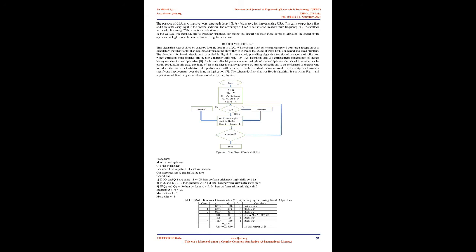Wallace tree multiplier. A Wallace tree multiplier is a hardware implementation of a digital circuit that performs multiplication of two binary numbers. Wallace tree multipliers were devised by the Australian computer scientist Chris Wallace in 1964. The Wallace tree multiplier lessens the number of partial products and uses a carry select adder for the addition of partial products. Wallace tree is irregular in structure, in which informal implementation does not supply a systematic method for the compressor interconnection, still it is an efficient method of adding partial products in parallel.